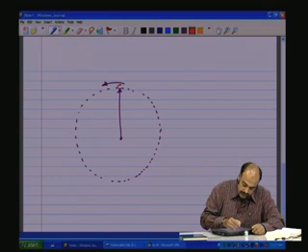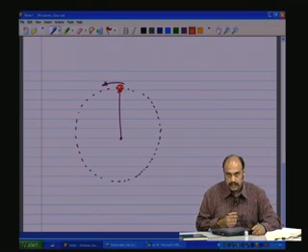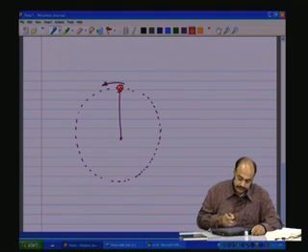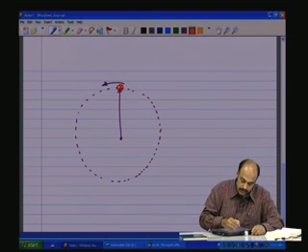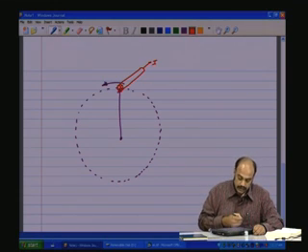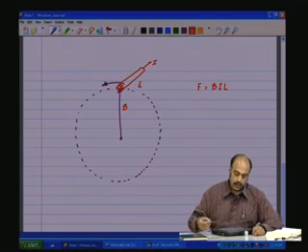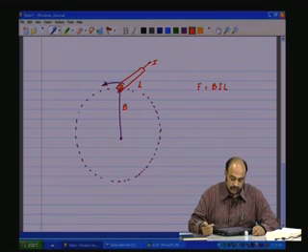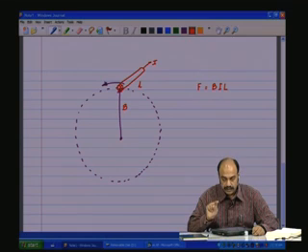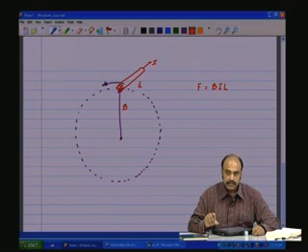Now as this is rotating, and if we have a rotor conductor, this rotating magnetic field is cutting the rotor conductor, and a current is going to flow through the rotor conductor, and that is I. There is a length of the conductor L. This magnetic field is of intensity B. So by the Lorentz law, you have a force BIL that gets produced, which will push the conductor in an orthogonal fashion, that is, to the direction in which the current is flowing and the direction of the field.